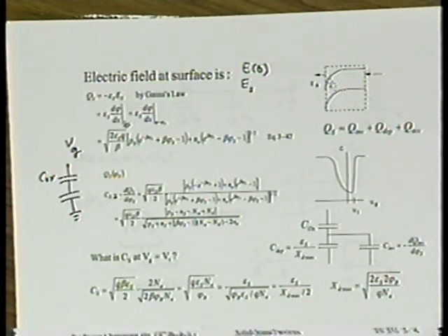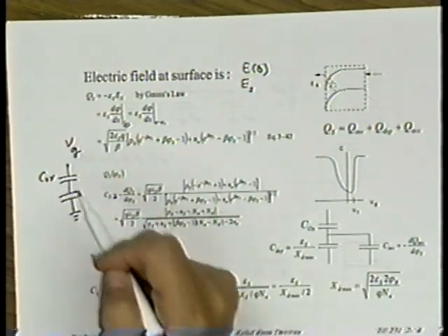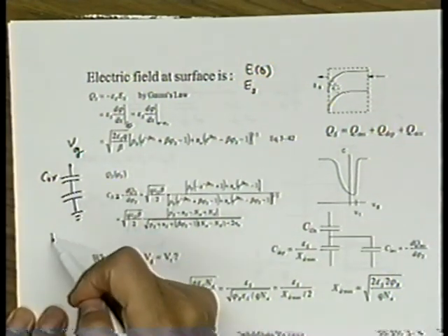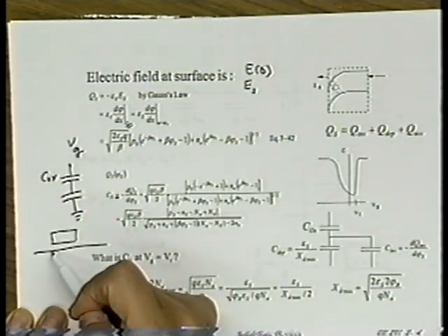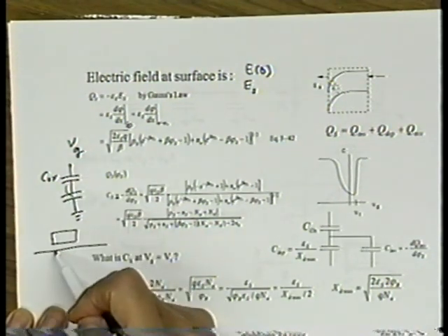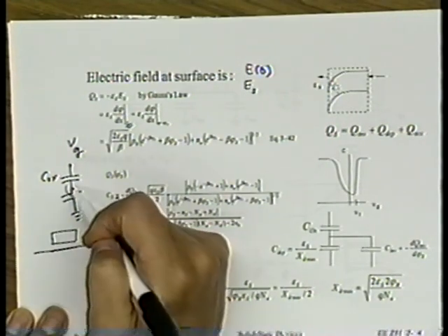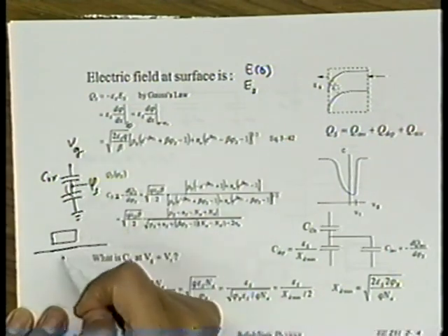Right? I'd like you now to focus on this point here. What is this point? If you don't think of this as an equivalent circuit, you think of this as the representation of the physical structure. There's a very physical interpretation of this electrical node. That is the interface. So the voltage here would be the interface potential, phi s.